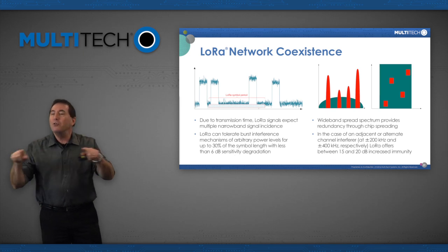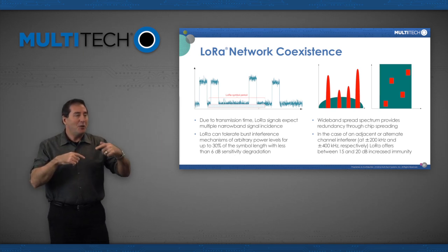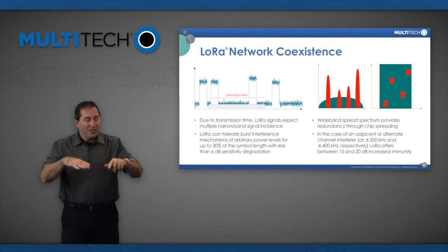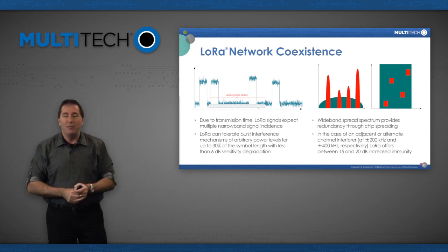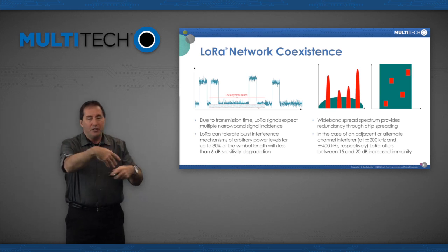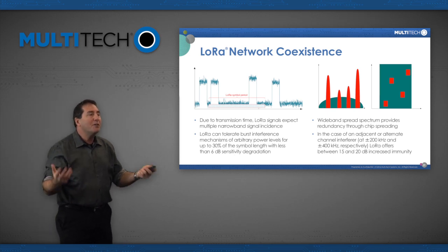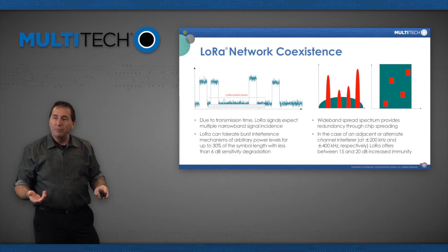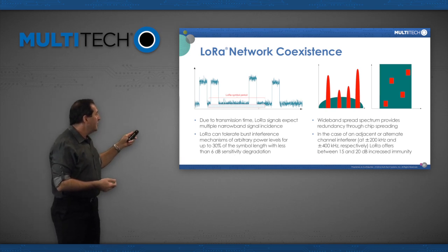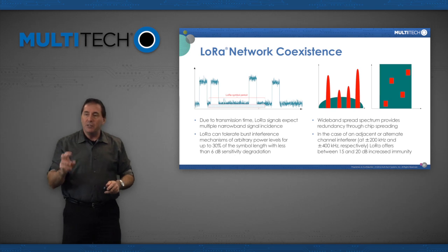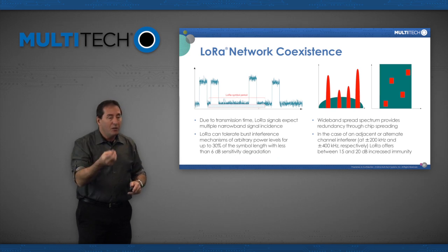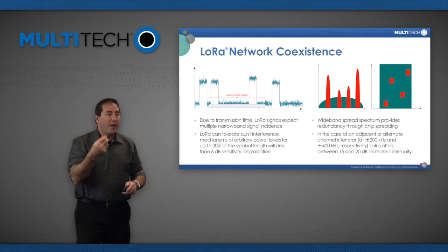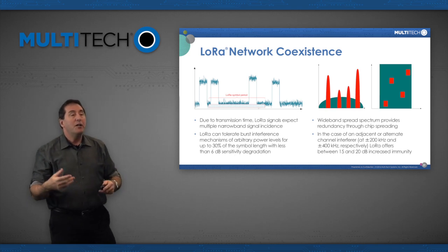To them, LoRa looks like noise. So the only thing that someone with an existing FSK radio is going to see is what appears to be the noise floor went up a little bit. That's all. They won't even hardly tell you're there. Whereas with LoRa, all this existing traffic, we're going to pretty much work as normal. It's not going to be a problem. And so this coexistence is extremely important for certain industries where we're trying to get LoRa adopted, like oil and gas, where there's a long-term existing approach, such as FSK, that might otherwise be an issue. Turns out it's not really.